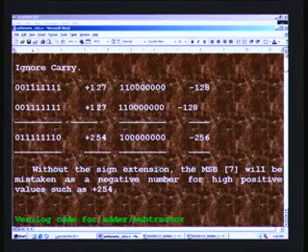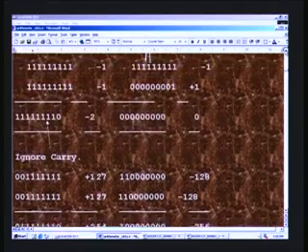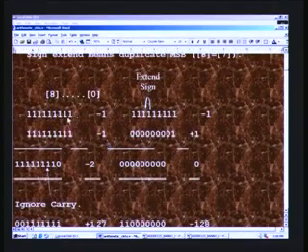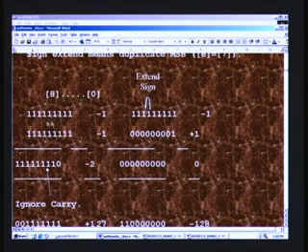We will prove that by one of these examples. For example, let us see here, we will take minus 1. In this case you have 9 ones here. What if I have just 2 ones alone? Will it still be minus 1? The answer is yes. So, that means I can duplicate the MSB, which is the sign bit in this case, any number of times, right up to infinity I can put 1.